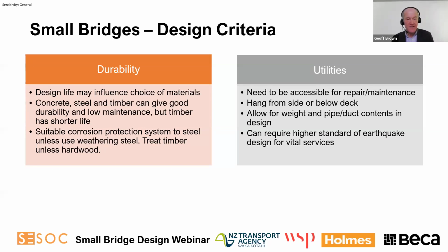And lastly, utilities need to be accessible for repair and maintenance. It's best to hang them from the side or possibly below the deck. We need to allow for the weight of the pipes and the duct contents in the design. And we can require higher standards for earthquake design if we've got vital services crossing the bridge.